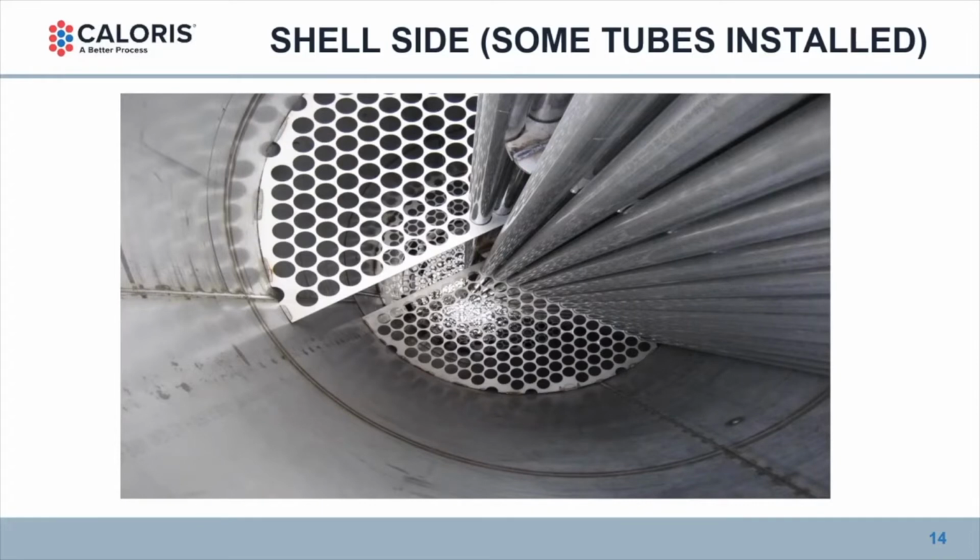And with them, our non-condensable gases are coming along with it. And as you condense the steam water vapor, on a mass basis and taking a volume, the non-condensable gases become more prevalent as it distributes towards the ends. And that's why the non-condensable gases will have a tendency to collect towards the ends of that heat exchanger.